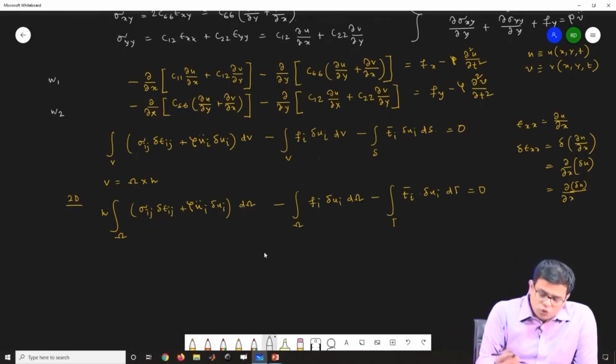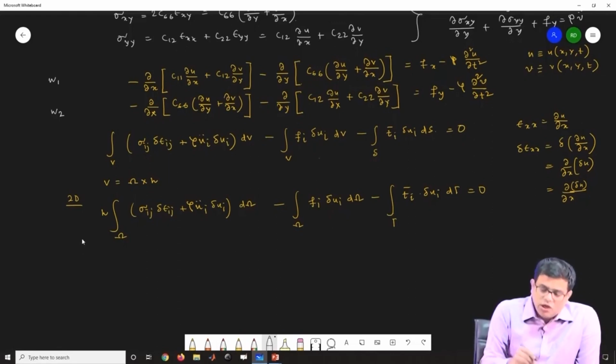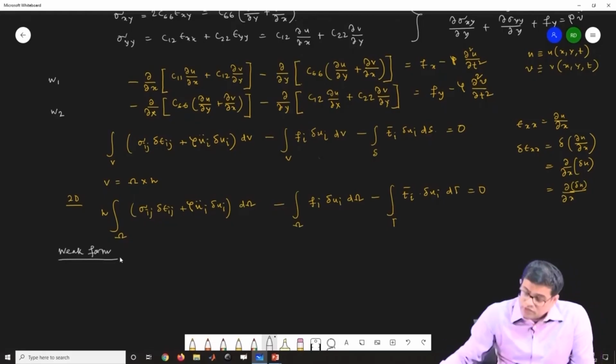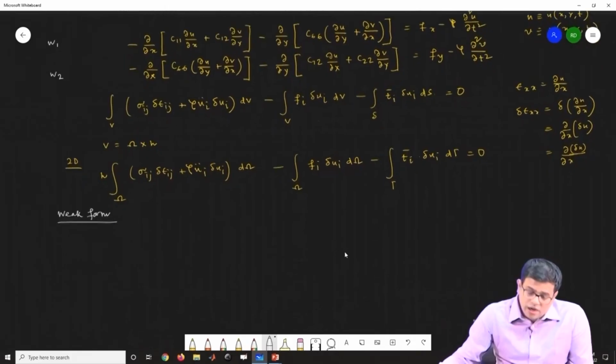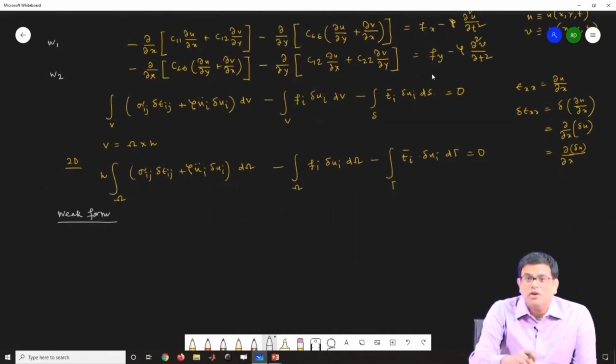If I do that integration by parts, essentially multiplying the governing equation with W1, the weak form will look like this. I just rearrange this equation, because if you integrate by parts, then a minus term will come, so the minus will cancel.